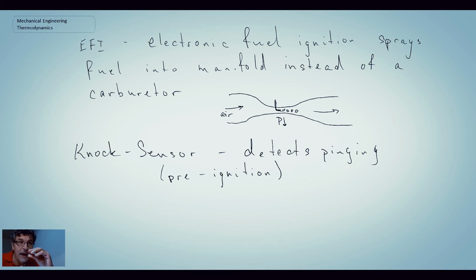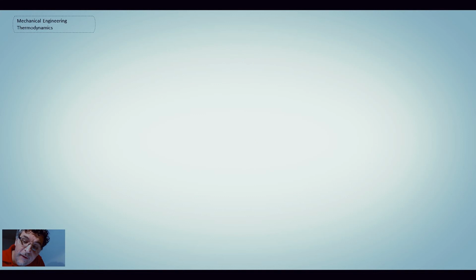Or what will happen is you get expansion while the piston is still moving up, and that will cause all kinds of problems for your engine. It could destroy it with time. And that's sometimes referred to as being knocking. And a mechanic would be able to detect the knocking of your engine. If it's really bad, you'll notice, because it's going to be a very, very rough idle of your engine.